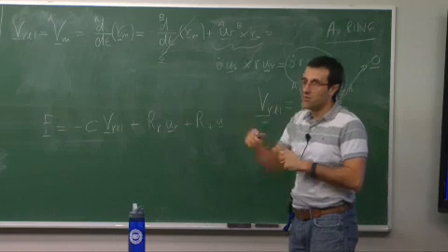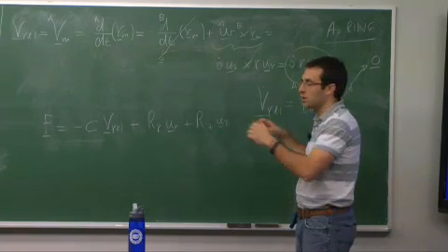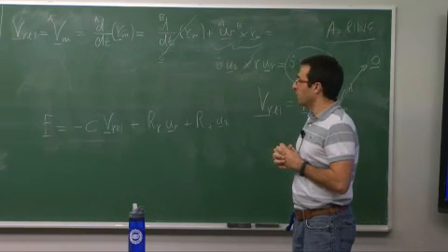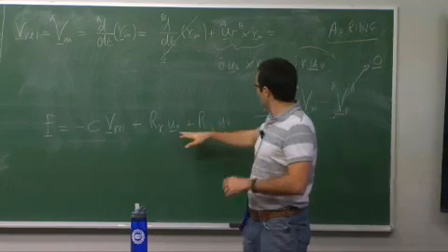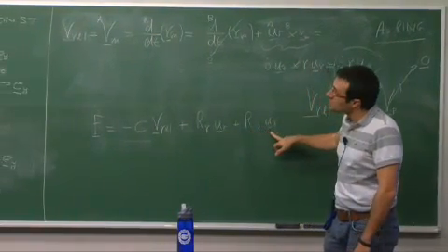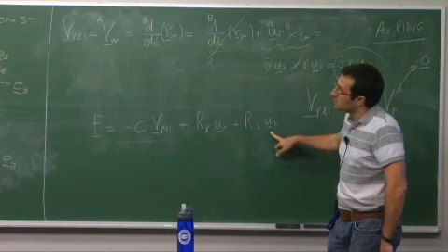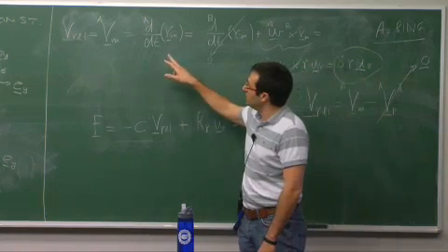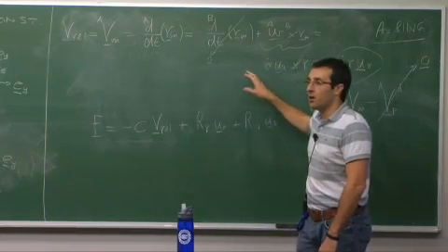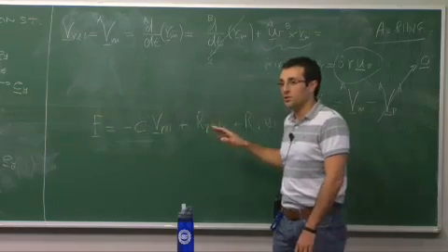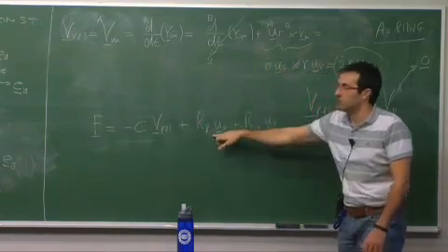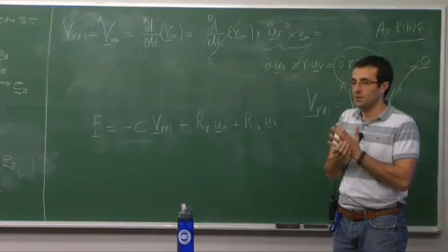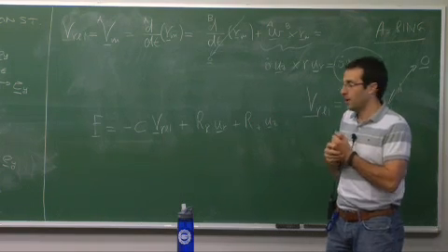You need to find the acceleration of P in the inertial reference frame and then equate the equation and figure out if you can really remove all these components. My guess is that these UR and UZ, you may be able to ignore them if you write the equations in the right way, and you will end up writing F equals ma only in the U theta direction, so that you get rid of, you don't really care about what these reactions are. That is my guess. But you guys finish it and let me know. Okay? Thanks.